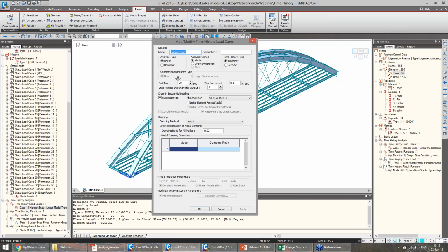As mentioned before, this is 90 meters in span, and these are all tensed. The tension force in the cables is as for the final model, for the final state. So I can use linear analysis for this.